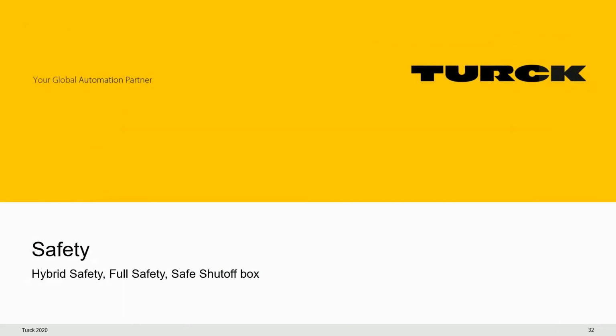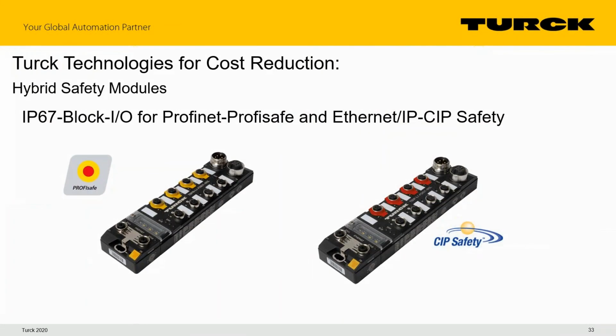And finally, we have the concept of remote safety. So we have IP67 rated blocks with PROFIsafe and CIP Safety. So we stop using multi-protocol Ethernet here. These are dedicated to PROFIsafe and PROFINET on one block, CIP Safety and EtherNet/IP on the other.